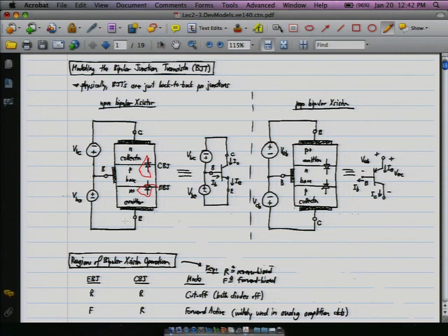One thing that you'll notice here is that this is doped more heavily. It's N plus in the emitter, and the purpose of that is that you want a high ratio of carriers injected from the emitter versus the carriers injected from the base. This is the standard model that we'll start from, and then we'll vary this and expand on it as we go.